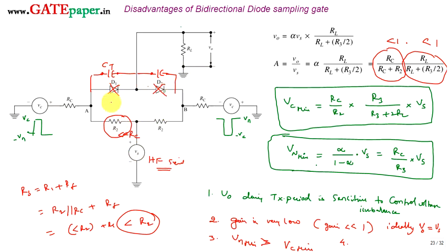At high frequencies diodes exhibit internal capacitance, of the type diffusion capacitance under forward bias and transition capacitance under reverse bias. Under reverse bias we expect V0 equal to 0, not a function of Vs. But if Vs is a high frequency signal, then the diode is going to present some transition capacitance, so V0 may be related to Vs, even during the non-transmission period.